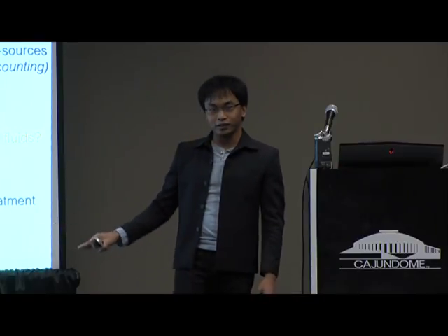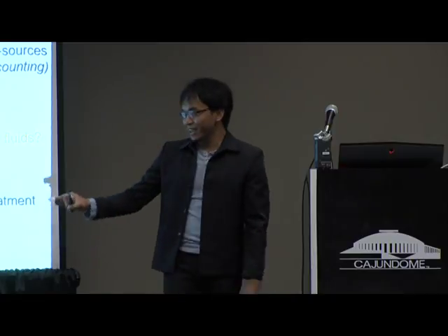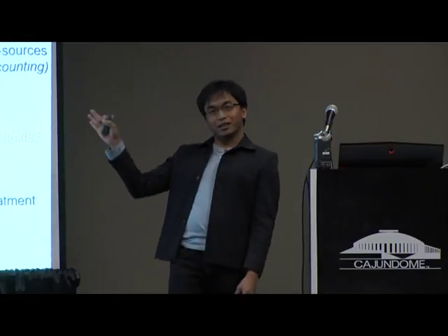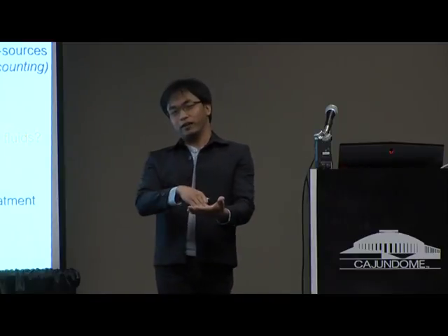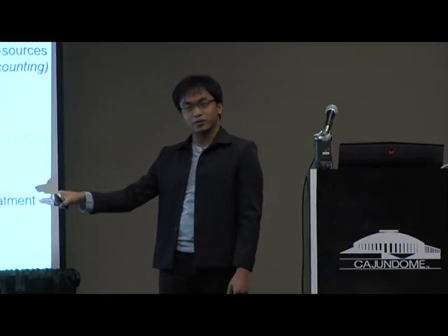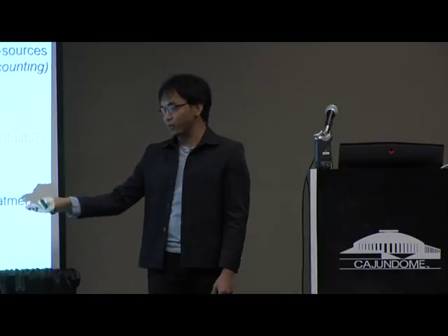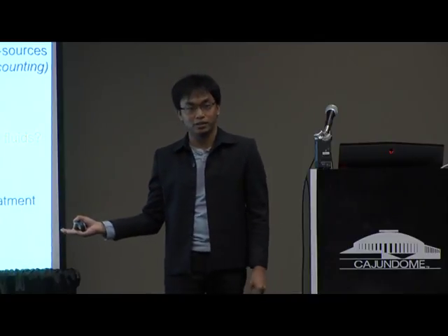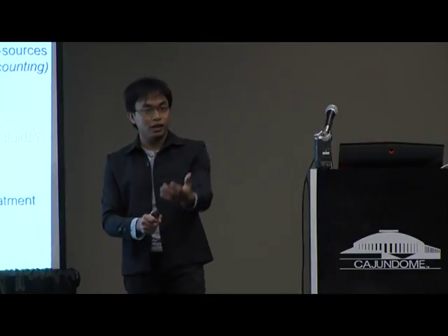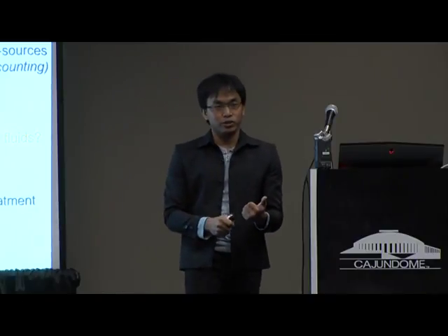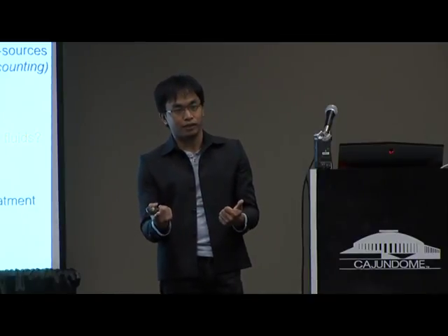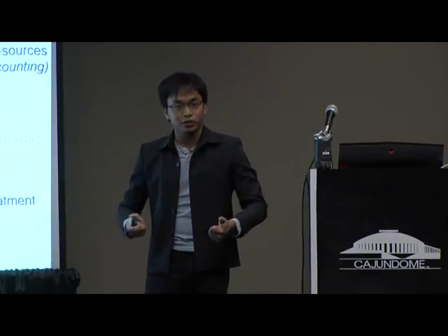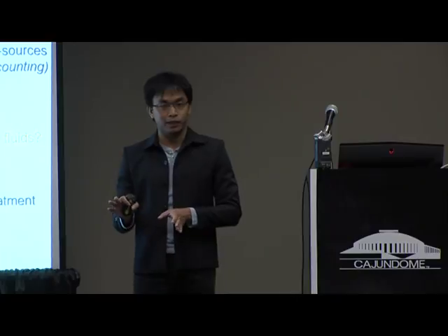And the fourth point here is that I'm borrowing this from Dhan, the base case for gaseous carbon source. This study focused on carbon source in the liquid phase, but perhaps the carbon source can also be a gas. In this one, the so-called methanotrophs. Perhaps they're also in the activated sludge. The idea here is that we can use methane that we are producing right now in wastewater treatment plants, feed it to the microorganisms in activated sludge, and use that as a carbon source to accumulate lipid.